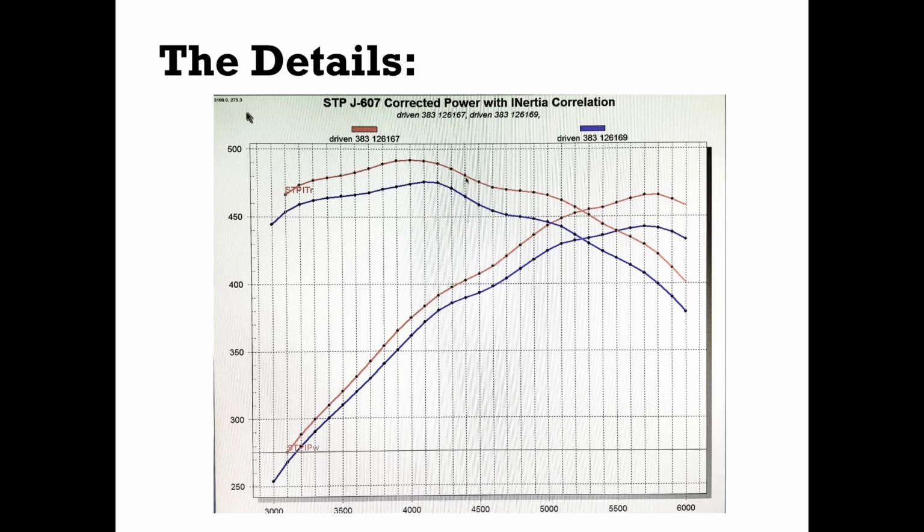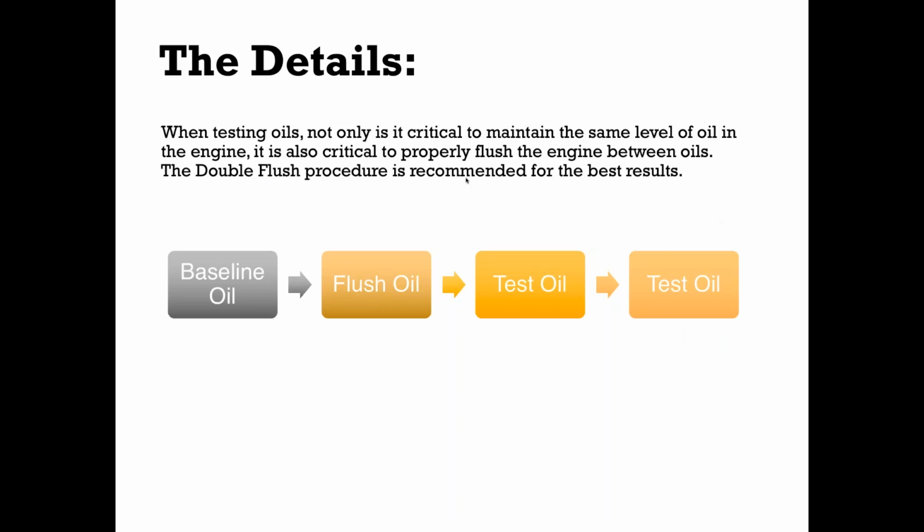So that's something to keep in mind to make sure that you're staying on top of when you're doing testing, to maintain that same level of oil, same volume of oil in the engine at all times. That way your results are reliable. And part of that process is you think about them weighing it in, how crazy that sounds, but you've got to remember when they're doing fuel economy testing, they're not rebuilding the engine between each oil. So you're having this same engine and it will maybe run in one day a couple of different oils.